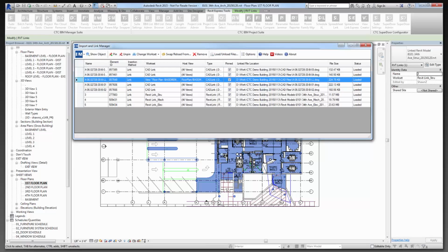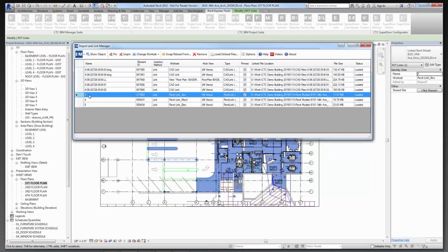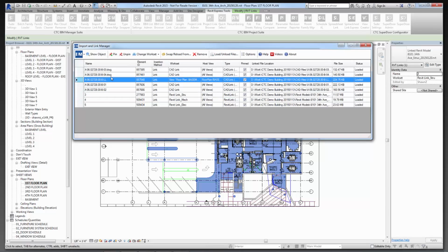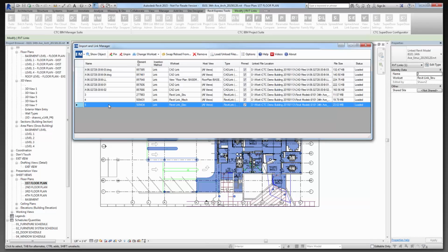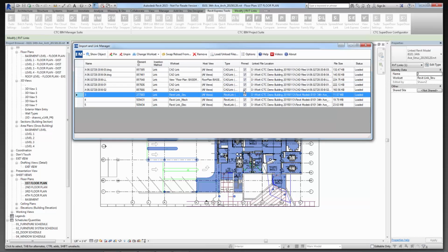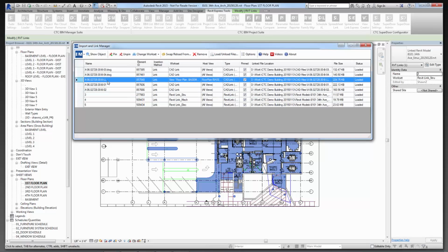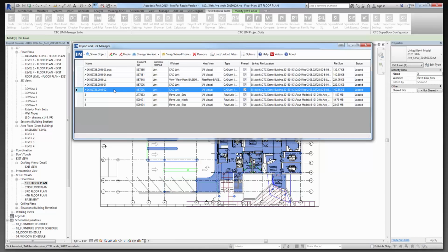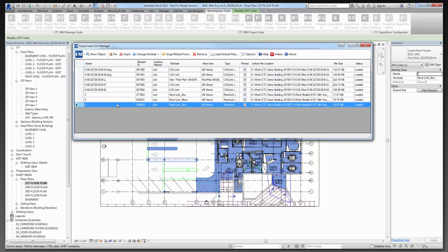Can link names be changed through this dialog box? So over here, we've got link names in the mix. And this actually does not allow me to author link names. At the moment, it just uses whatever the link name is from Revit. You can, of course, augment those from the Insert Manage Links dialog. This one here does not actually let you change the names of the links. It uses whatever the file name is. When I'm converting this to a link here, you'll notice that it strips out the DWG when I converted it. Of course, the Revit links themselves come in as numbered links, but I cannot actually augment that here. That is what it is.